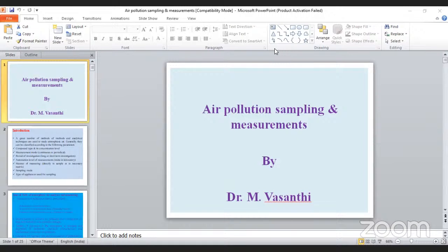And for example, if you take the evening sample around 4 or 6 o'clock and you get some X value, can we fix that value as the pollutant level of that particular place? Whatever value you get may not be the same in the morning, afternoon or night. Then how will we report it? How can we do the sampling?